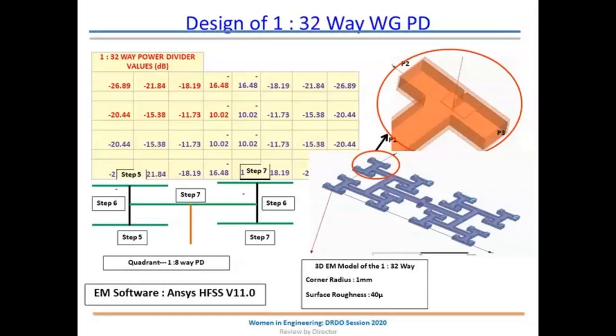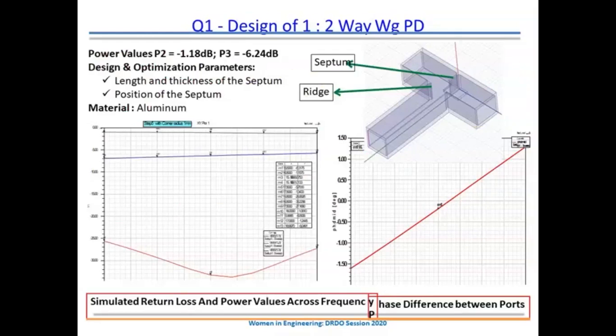The software can also carry out sensitivity analysis, in the sense that when fabricating, if there are certain tolerances of some microns, what is going to be the effect on your final antenna performance can also be analyzed in this software. That gives us a fair idea of what values you can tell your fabrication guy, telling him, okay, the performance will degrade if you exceed this tolerance value. So with this software you can do that, and this is one of the performances of an antenna.